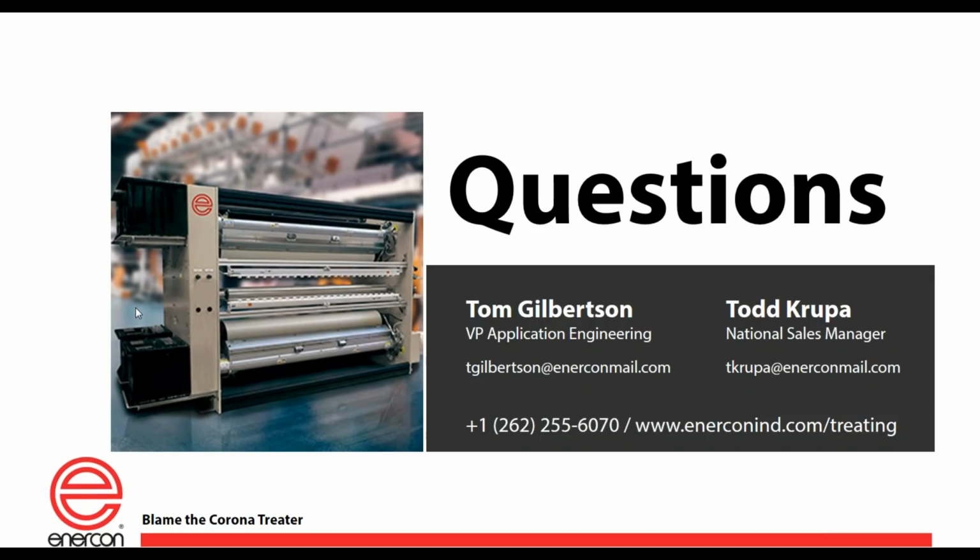Couple questions related to Dyne level. Generally speaking, is there a typical rise that you see in Dyne level after treatment? And what expectation of increasing watt density should we see after treating, say, at a Dyne of 36 to 38? So again, looks like trying to predict. Yeah, it's really hard to predict. If I had to throw a dart at this, based on experience, if you have polyethylene film, for example, and it's coming to the press at 38 dynes, and you're running through the treater, it likely comes out of the treater at a watt density of 2. You might be in the low 40s. It might be 42, 44, something like that is pretty common.